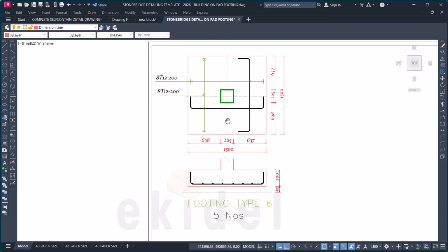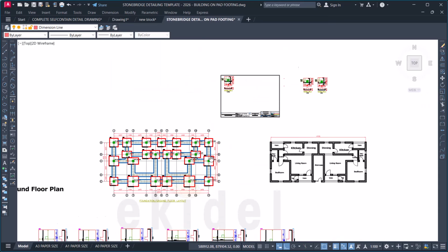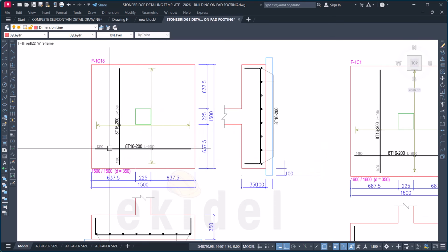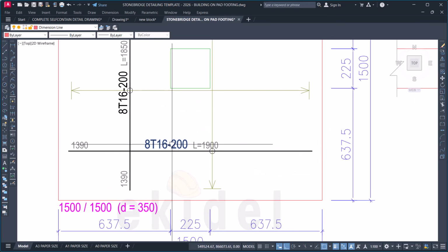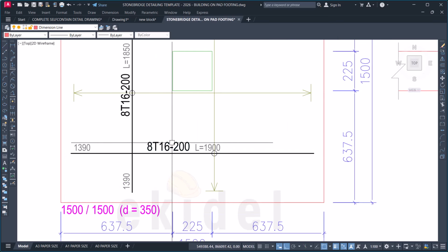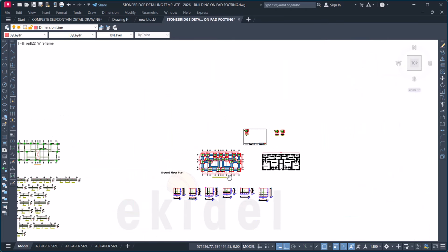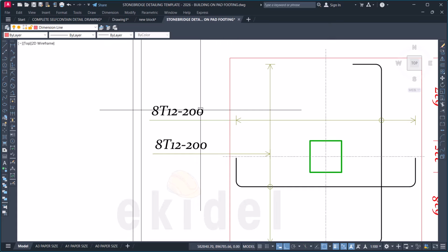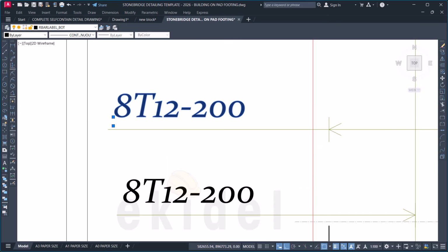Okay, that's fine. So with this now, look at what you have from your design report. You have Y16 at 200. So we are going to transfer our design report size for our reinforcement and the number to this custom one here. So we can see that this is 12, so change it to 16 because this is a 2-story building design. So put 16 here, and again come here and put 16.